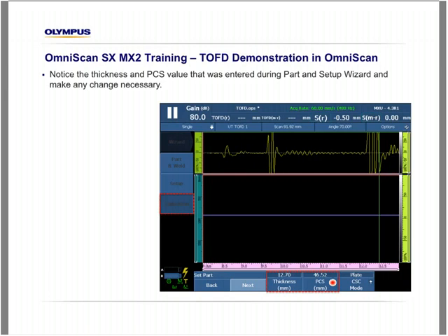No matter how hard you try, the only way to lock the probes in the scanner is visually using a ruler and lines on the wedges, but historically, I would say operators can get within maybe 3 or 4 millimeters of this actual distance. So this function is going to change a theoretical or mathematical PCS to the real PCS so it is known to the software.